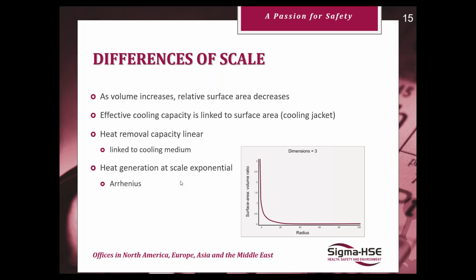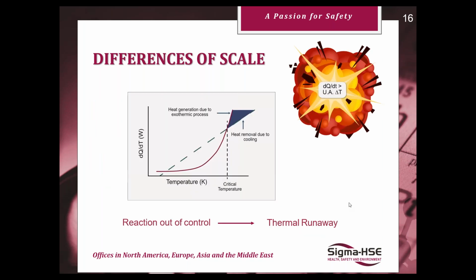As temperature increases, the rate of the reaction is also increasing. So a runaway reaction is only going to get hotter quicker as time goes on until it exhausts itself. So this relationship can lead to a runaway where the cooling of a reactor is no longer capable of treating or removing the heat from a system.